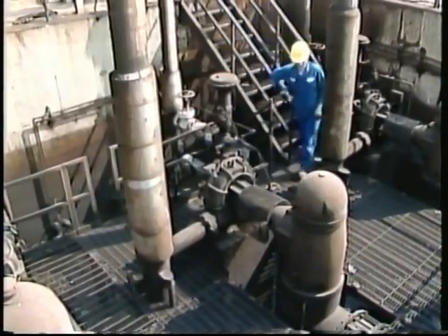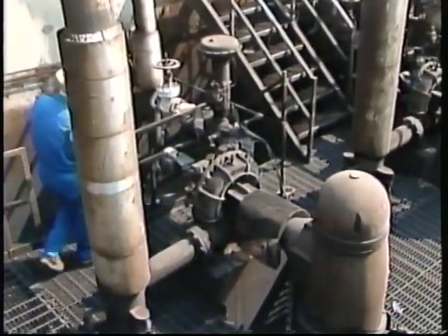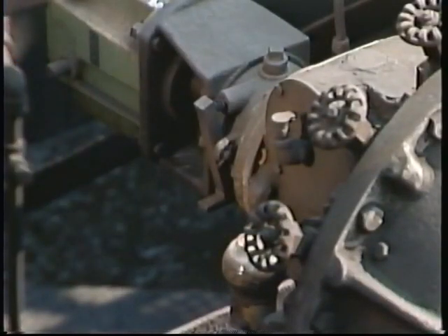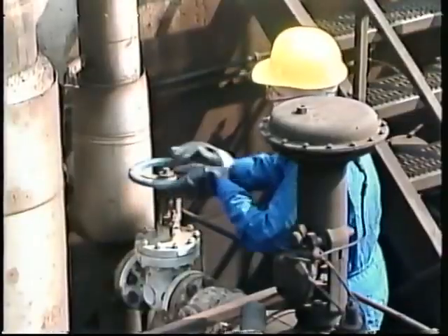The specific steps for a normal shutdown can vary from one facility or turbine to another. The procedures we'll cover apply to most cases, but you should check the operating procedures for your own facility to be sure you know exactly how the turbines you'll be working with are shut down. In some cases, the first step is to manually trigger the overspeed trip. This shuts off the steam supply and allows the turbine to coast to a stop. It also tests the manual trip mechanism. Then the operator proceeds with the shutdown by closing the throttle valve.